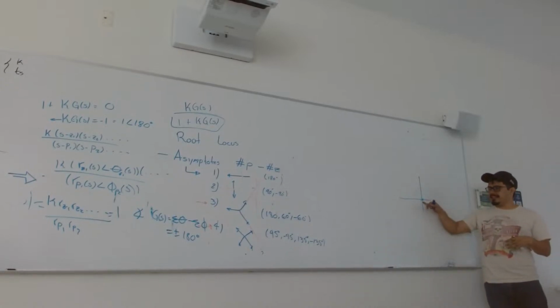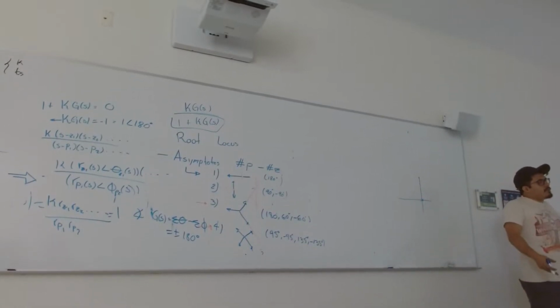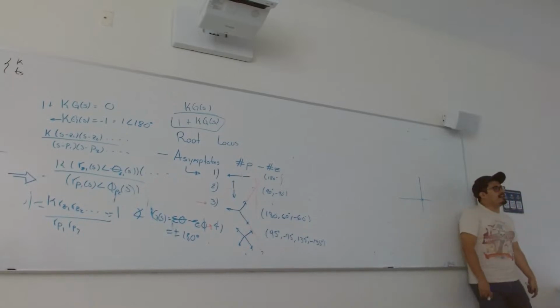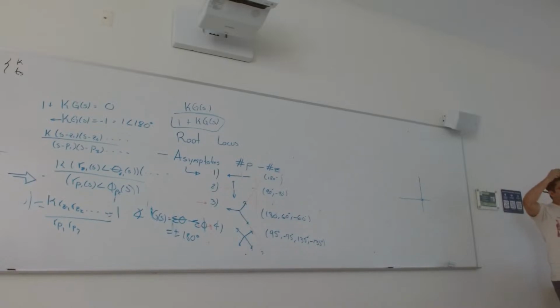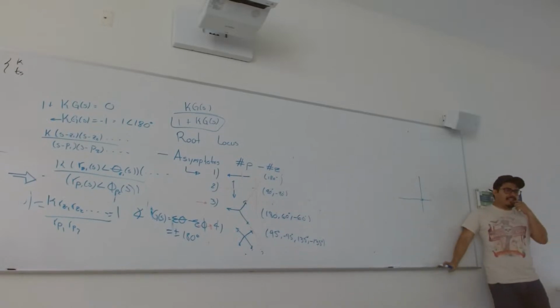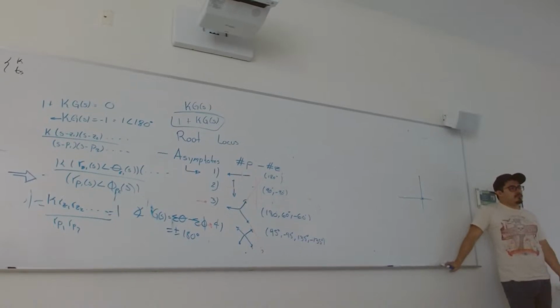So sometimes you may need to use a lag compensator, which is the passive PI. The lead compensator is the passive PD, and the lead-lag compensator is the passive PID. We don't have those restrictions anymore. Having active systems is really cheap.